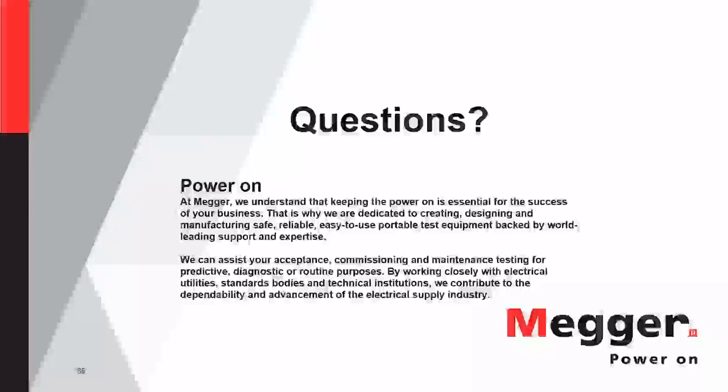Okay. All right. Another question was from Jonathan. He asked, should the transducer be calibrated on a certain interval? And if so, what is the recommended interval? So this is the same thing we kind of previously answered. There's not a standard one. If you're really worried about it, our standard is once a year or so. If I was a manufacturer and you're pumping out 10,000 breakers a year, you're operating that transducer a lot, so they're probably going to calibrate once a year.